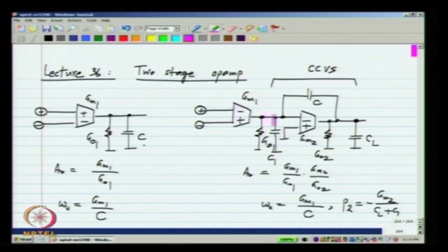So, we have all the things that we need to understand this topology. All we have to do is to implement this at the transistor level. Now, how do we go about doing it? First of all, you see that the input part of it is the same as before. We have a transconductance which was driving a capacitor, now it drives a current controlled voltage source. We have already spent some effort coming up with topologies for this. So, we will use our single stage op amps for the transconductor. A single stage op amp is nothing but a transconductor, and that we will use in place of GM1. Now, we have to realize this transconductance GM2 and connect the integrating capacitor across it, that we will see how to do and complete the circuit.